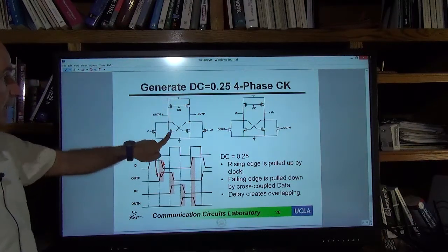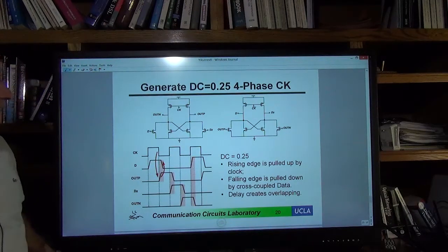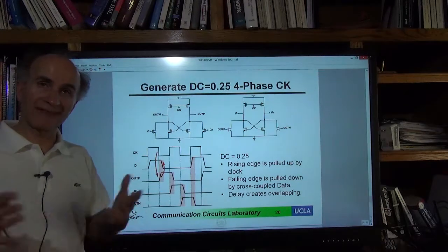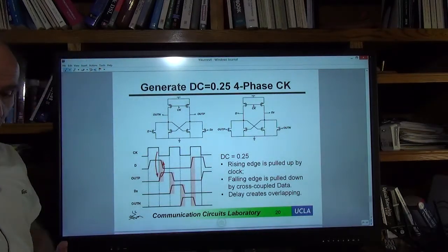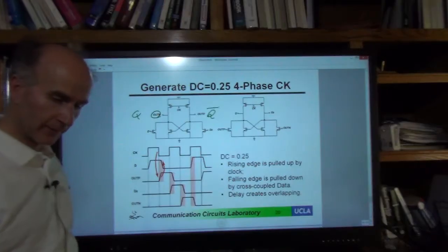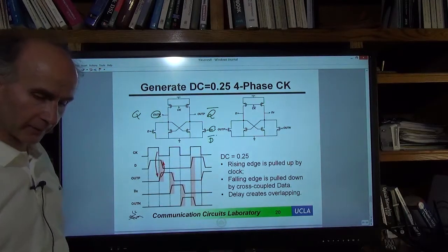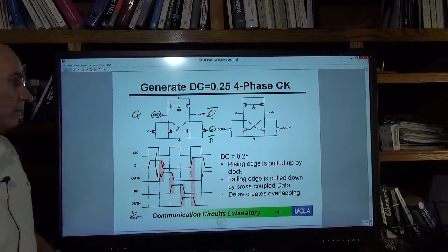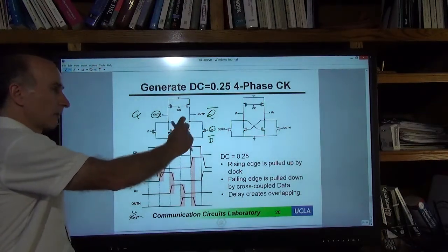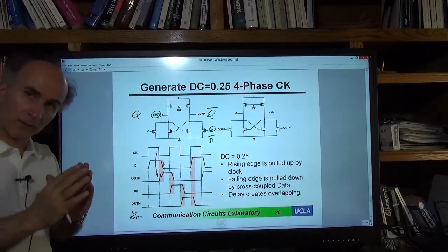So, this circuit diagram is an example of poor drawing. So let's look at it. As usual, out P and out N shouldn't be like that, right? It should be V out or D out or something, right? If you want to look at more of a digital circuit, usually we call these Q and Q bar, right? And these would be D and D bar, not DZ. It should be D bar, okay? And in terms of everything that I said before, this spacing has to be minimized, and so does every other spacing, right? Everything has to be squeezed.